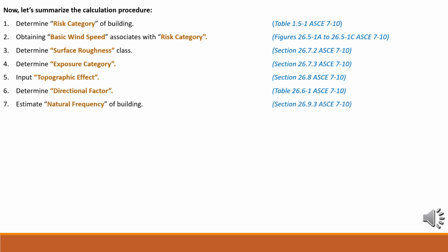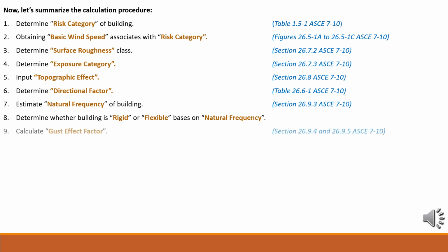Estimate natural frequency of building. Determine whether building is rigid or flexible based on natural frequency. Calculate gust effect factor.